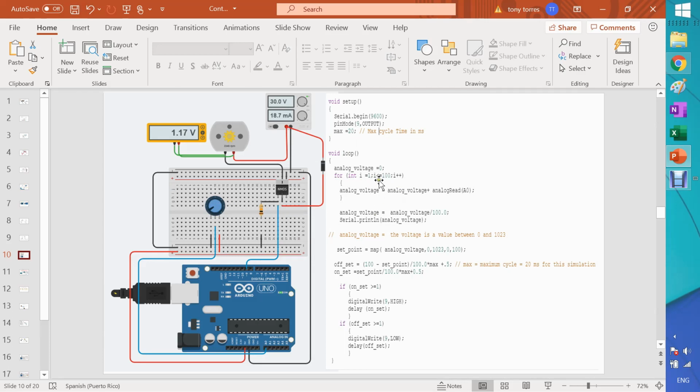I couldn't do this. The Arduino is fully dedicated to deal with that line, but in this setup it worked perfect. For example, I'm averaging. Let's say that this signal is kind of noisy and you want to average it. You want to have 100 values. So this is how you do it. Here you are having 100 values. You add them together, and then you divide by 100. I'm doing a little floating math here. Divide by 100.0, and then I print that value with the carriage return.